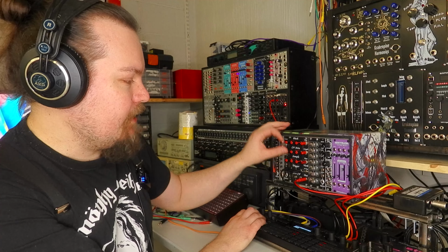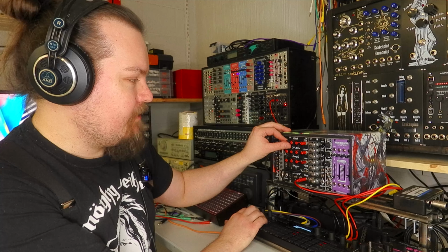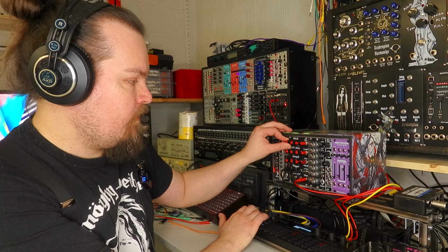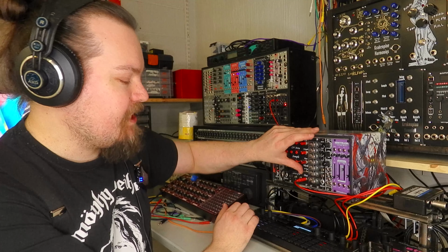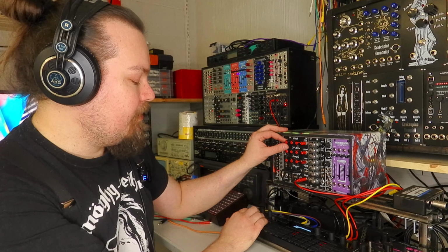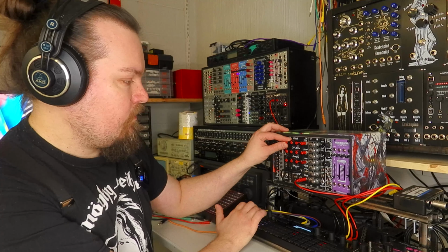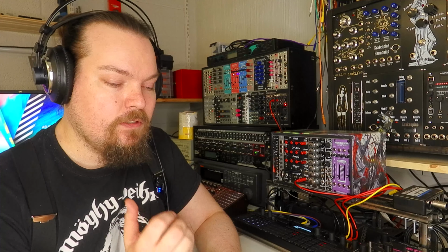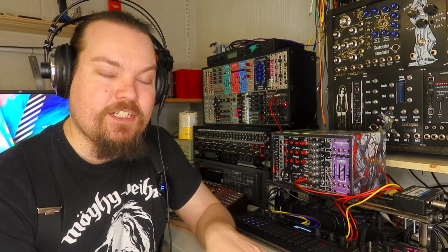Then there's also this CV type. Now if I play a sample and play with the pitch knob, when the sample is playing it doesn't change the pitch, but if I put it to type B, you can change the pitch while the sample is playing. This is for if you want to put control voltage in, basically some random or LFO there. You can have a differently pitched sample every time, but the sample doesn't change pitch while it's playing. It sounds much better if you want just a steady sample, but in different pitches.